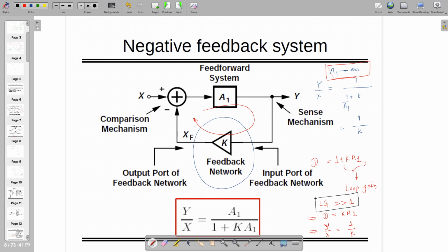By the way, this definition and all these numbers are relative. When we are saying infinite, actually it's not infinite, it's a sufficiently large number, and that is going to be decided by your application. Slowly we are going to move on to different real-time applications of analog circuit designing, which are very interesting, like oscillator, ADC, DAC, or PLL. Then we have to define that number. That number has to be some finite number, and above that number is considered as infinity. So we are going to set the budget, or make the required amount of gain, required amount of bandwidth, and other things, pole zero placement, all these things accordingly, right? So let's start with the theory that loop gain has to be much higher than 1.